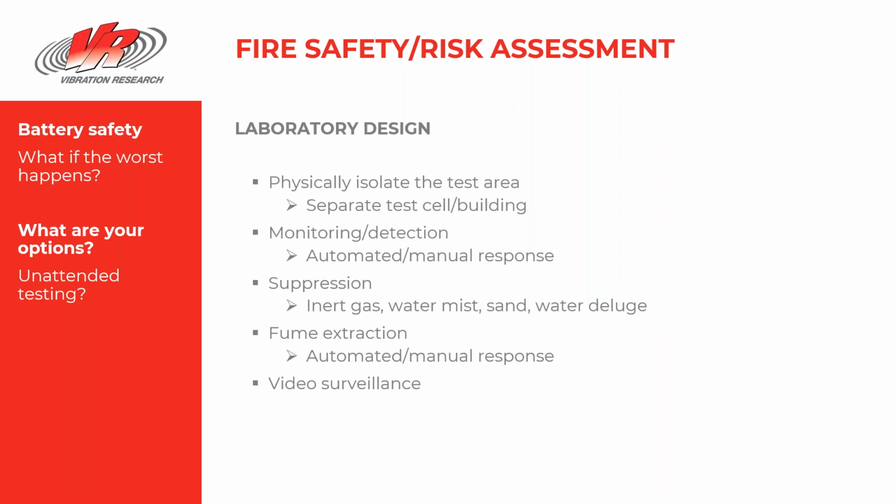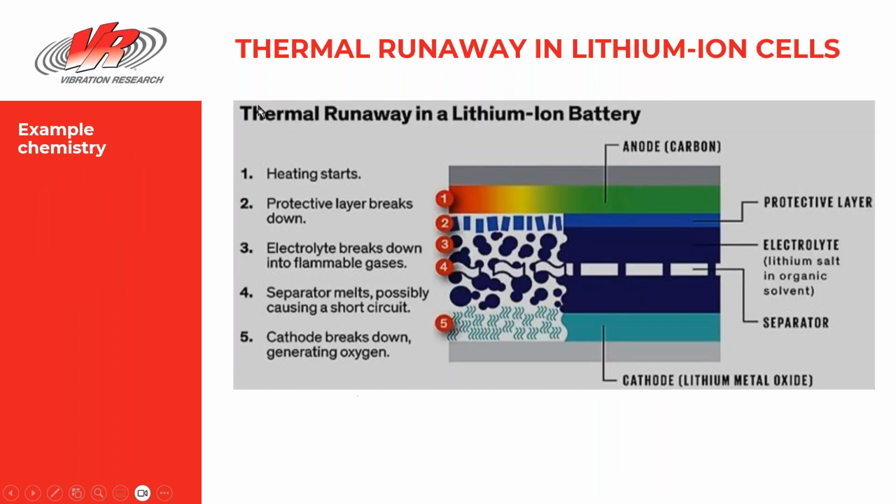There's a lot of fumes associated with lithium battery fires, so make sure you've got an automated or a manual response system for switching on that fume extraction. And then the other thing is ensure you've got video surveillance so you can see what's going on.